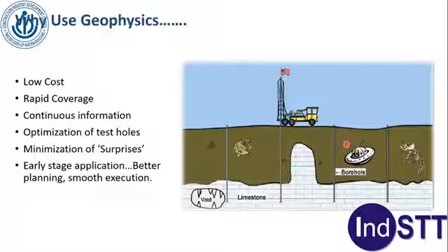So we'll just start with a few trenchless objectives. What do we want to find out in a trenchless project investigation? First is safe bore path. Okay, so it is desirable to have information on existing utilities like pipes, cables, etc. before finalizing the safe depth and alignment of the bore path to ensure safety of equipment, personnel and existing utilities.